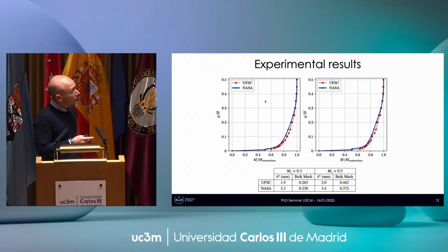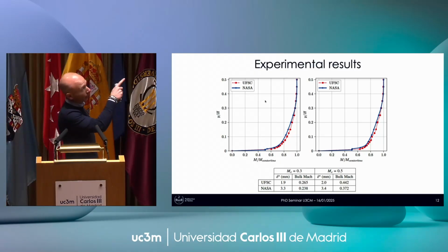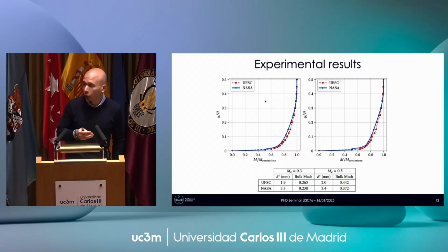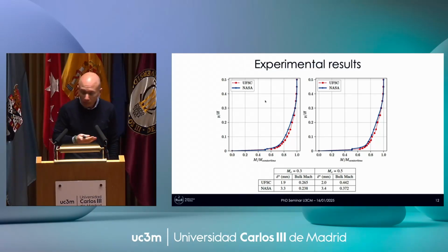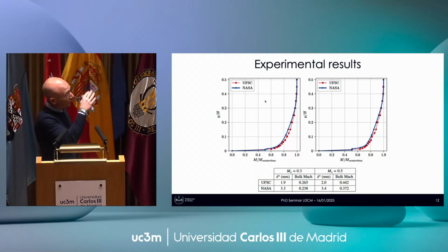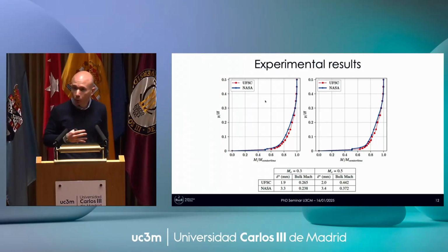Then what came out is that if we match the Mach number, the center line, all the bulk, so the average, still some properties of the boundary layer close to the surface are different. In particular, we focused on delta star. And we saw that there was about a factor of about 2 between the two delta star.